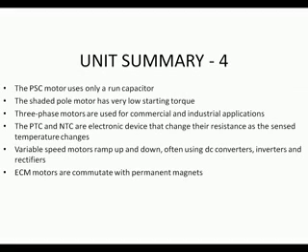Three-phase motors are used for commercial and industrial applications. The PTC, positive temperature coefficient, and NTC, negative temperature coefficient, are electronic devices that change their resistance as the sensed temperature changes. Variable speed motors ramp up and down, often using a DC converter, inverter, and rectifiers. ECM motors are commutated with permanent magnets.